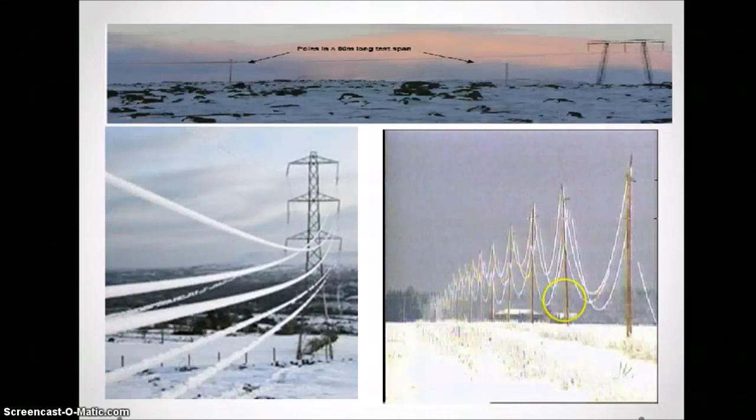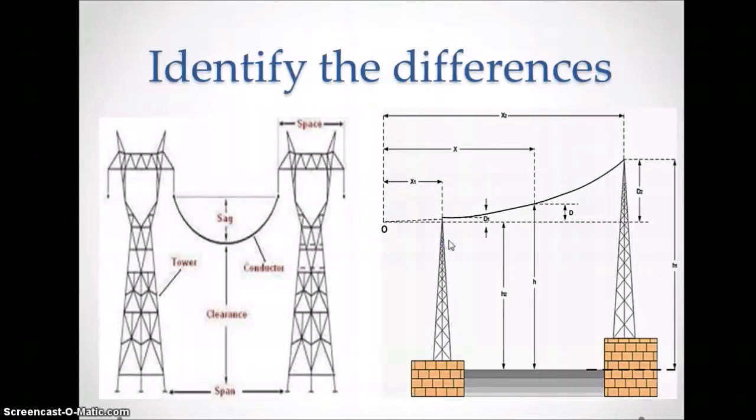So as of now, we have seen the conductors, poles, and towers, and can you see these conductors? These are white in color. It is not the conductor color. We have ice weight, ice covering the conductor. Here it is having wind. So the conductor will possess 3 types of weights: its own copper weight, this ice weight, and this wind weight. Considering these 3 weights, we have to choose the conductor for our experiment. Thank you.